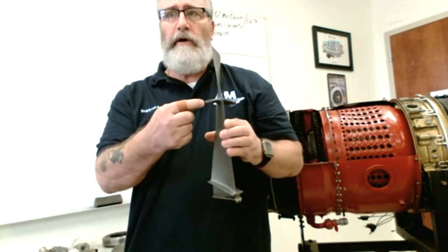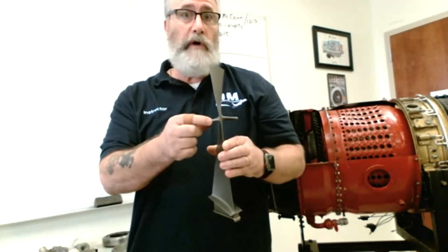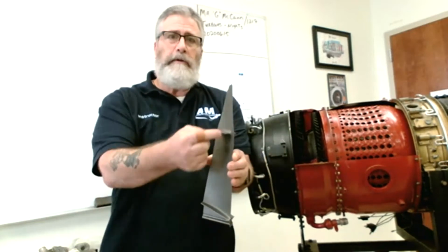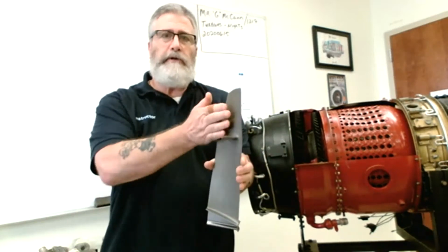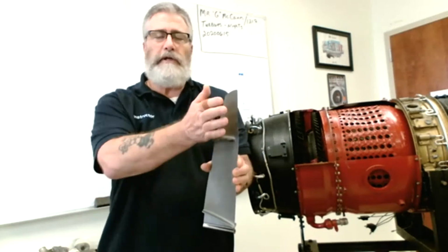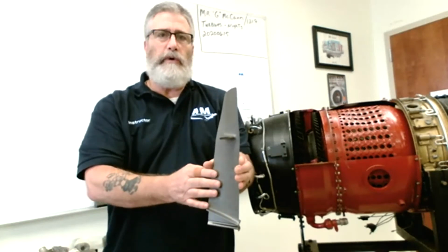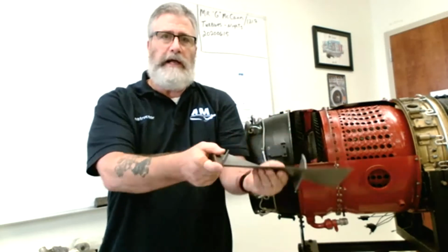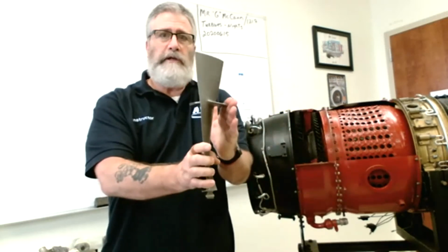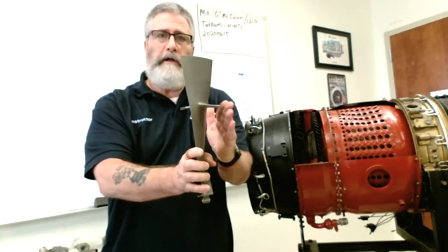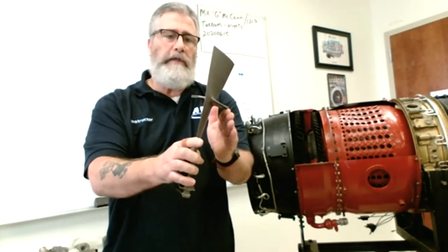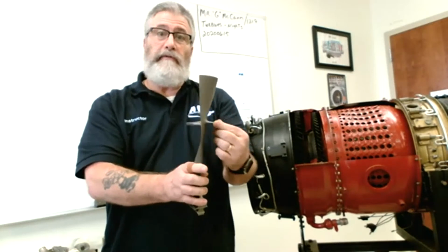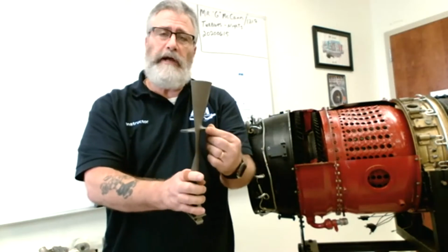So these items right here are called a mid-span shroud, all right? It's a mid-span shroud. They stiffen the blade, and they also help to channel the air in the direction that it is intended to go. So sometimes because these go around the entire inlet, these touch each other, so they have a tendency to wear. So when these wear or they overlap, then that damage is referred to as shingling, all right?